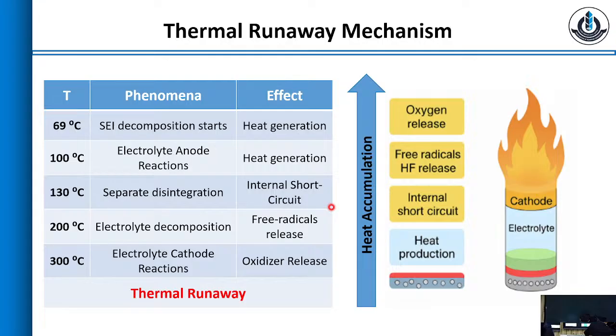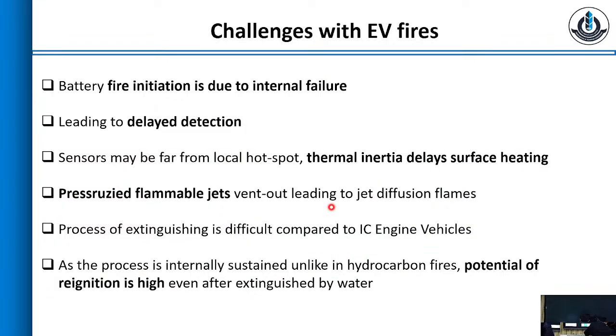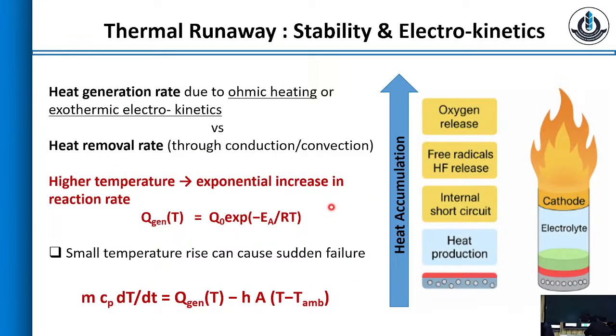The more accurate your model is, the more effectively it can be used for battery optimization, like battery pack optimization. To model these accurately, you have to know what these processes are, which are still being explored. Basically, once your heat rejection is slower than your heat generation, you start accumulating heat, and it will ultimately lead to thermal runaway failure.